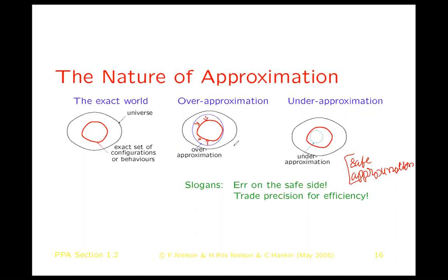So you may want to put in a lot more time to generate an optimal hardware design. There possibly you may be fine with slightly higher complexity algorithms. But there is a cost to pay, because even for small designs, when we do what is called synthesis, it takes a few hours to synthesize the design.